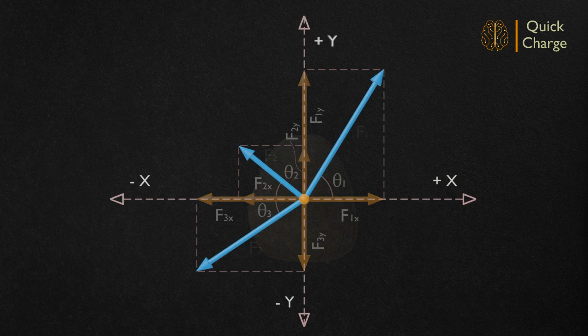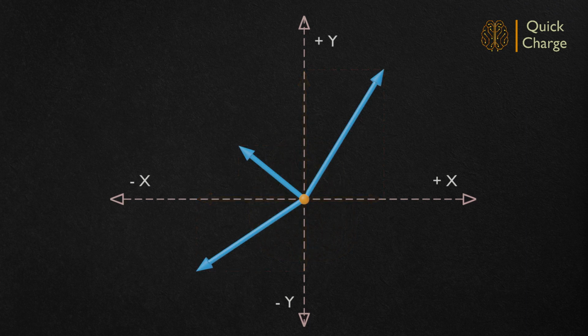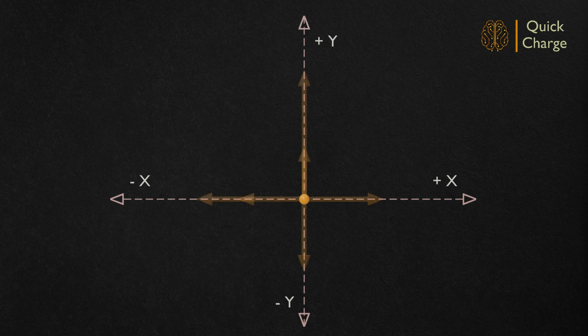This process transforms the inclined forces having different orientations into a group of collinear forces in horizontal and vertical directions. We know that for collinear forces, the algebraic sum of component forces yields the resultant. Components along positive direction of the axis would be considered positive and those along the negative direction would be considered negative. This should be accounted while finding out the magnitude of the resultant.